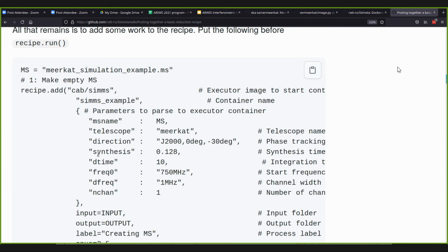So there's many packages here. I'm going to show you just how to simulate, for instance. Let's say you want to simulate your UV coverage. The simulation itself is done through a wrapper script called SimMS, and that calls on CASA internally, which writes out an empty measurement set for you that has fields in direction that you can specify as directions here.